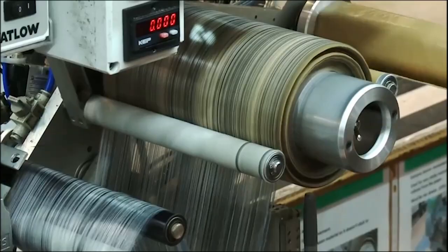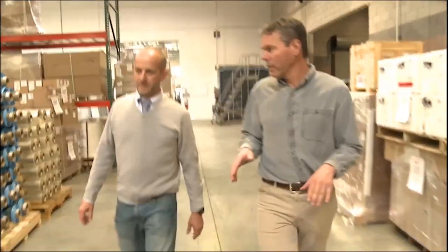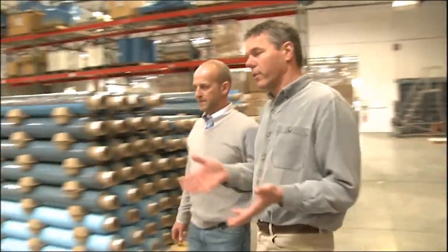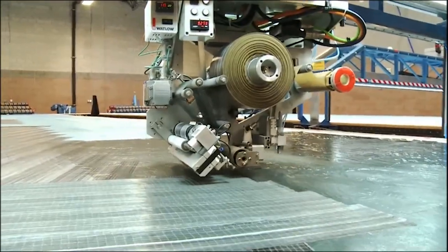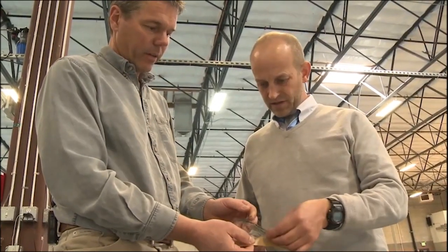It's the lightest composite tape made because it's 1 filament thick. So we need this machine in order to just get it off the roll and get it down where we want it. There's just nothing to it. It's just got no substance whatsoever, has it? Right. So how many layers of this stuff? Because obviously like that, it's got no strength. Well, in the corners of the reefs, you could have as many as 60 to 100, depending on the weight of the tape. In the body of the sail, a minimum of 6.